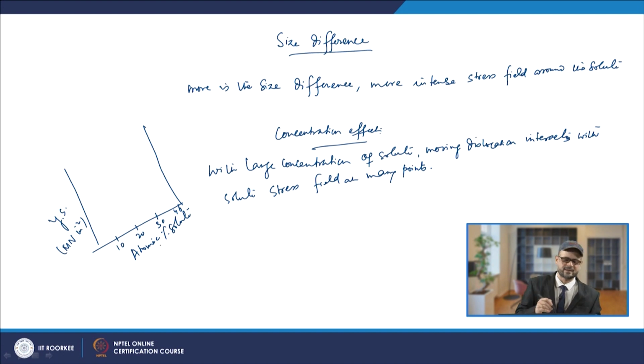So, this is percentage. What is seen in that case, if you are using the copper crystal and strengthening this copper crystal with other atoms, suppose this is 50 mega Newton per meter square, 100 mega Newton per meter square, 150 mega Newton per meter square. What is seen is that the graph goes like this if you go for zinc, and for nickel this is the graph.